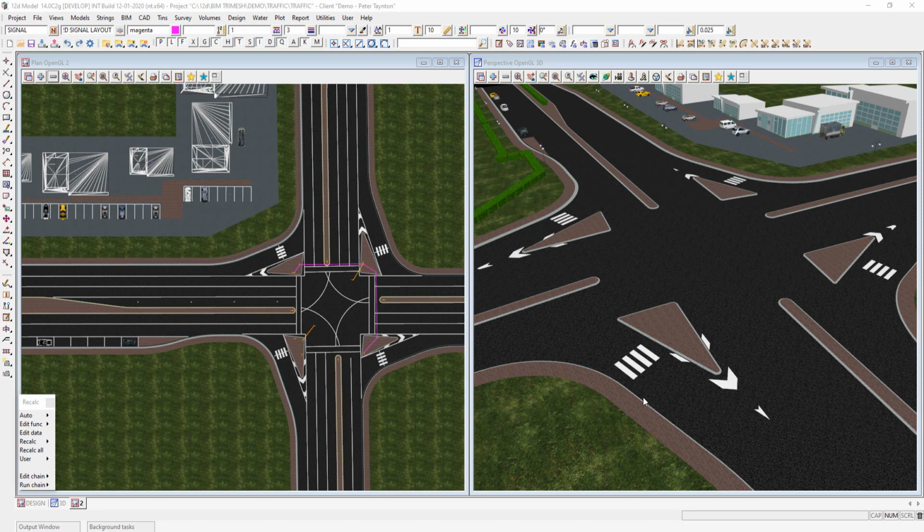The definitions are stored in a standard file called 12D Trimesh nodelink.4d, which is to be found in your setups area. The file can be copied from here to your user or working folder. The format is XML. The Trimesh shapes are applied to strings in relation to vertices and segments, so it is therefore imperative that the strings you use are valid strings. So no null levels, vertices that cross over or go back on themselves, or closed strings that are not supposed to be closed.